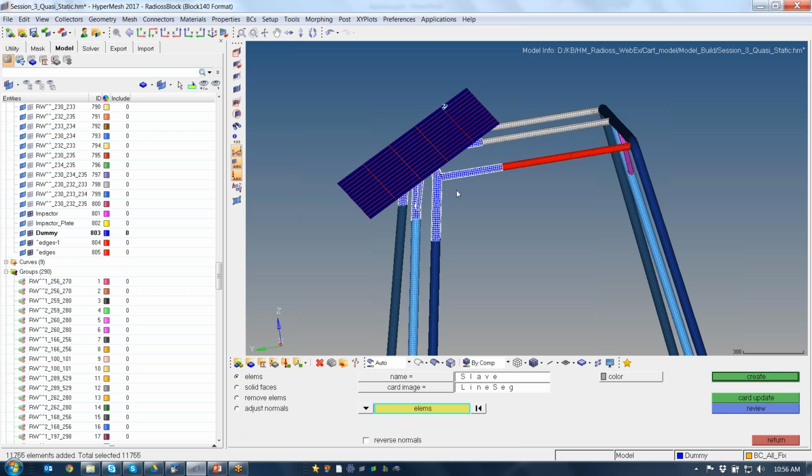And this is also one of the good points to keep in mind. When you have two surfaces and you have to make one master and one slave, it is normally a question of which has to be the master and which the slave. The generic approach has many guidelines depending on the materials and the load application member.